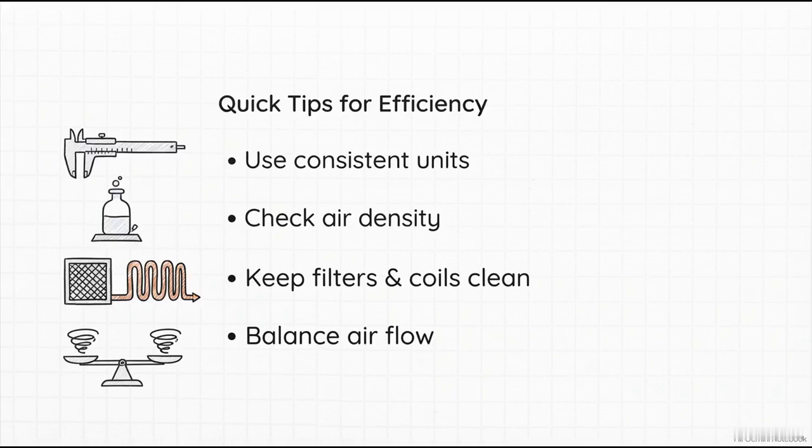A dirty filter acts like a literal wall, spiking your static pressure. And when static pressure goes up, the brake horsepower required goes up right along with it. That means your system works harder, chugs more electricity, and burns out way faster, all because of a little dust.